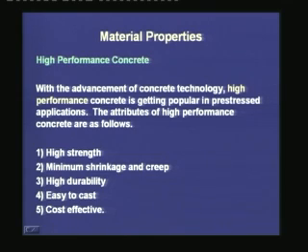The attributes are, first, it should be of high strength. As I said before, the primary requirement of concrete in prestressed applications is that the concrete should be of high strength. Then the second criterion is the minimum shrinkage and creep. The third is high durability. The fourth is easy to cast, and fifth, it should be cost effective.